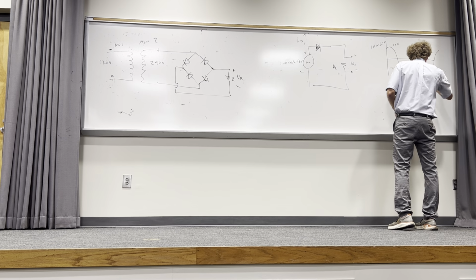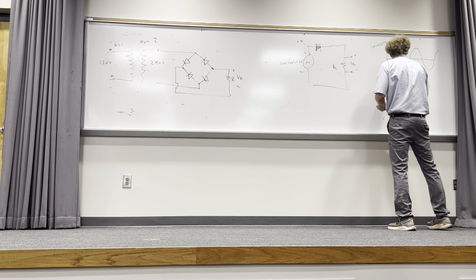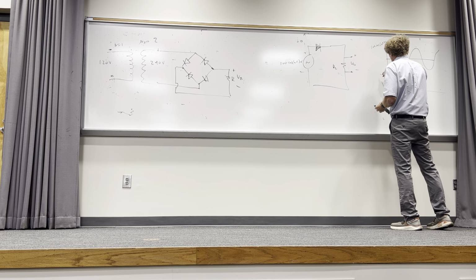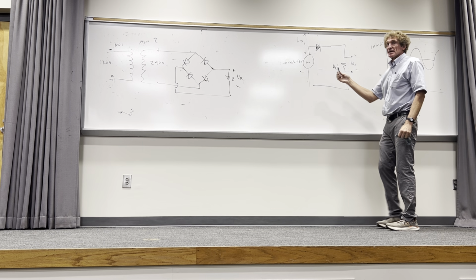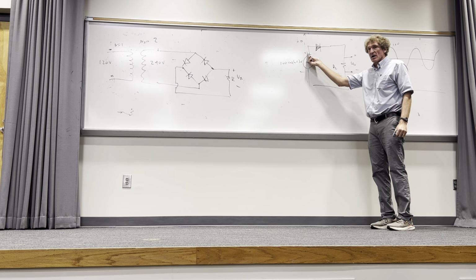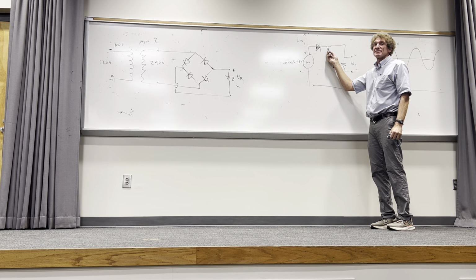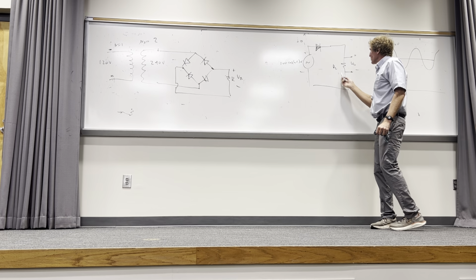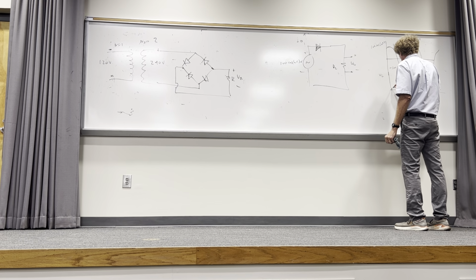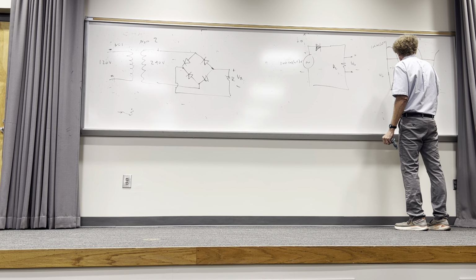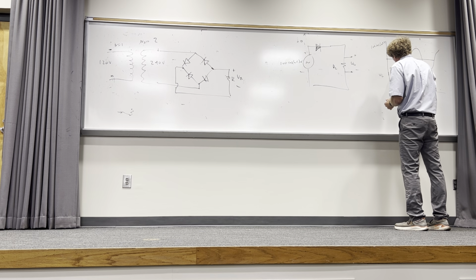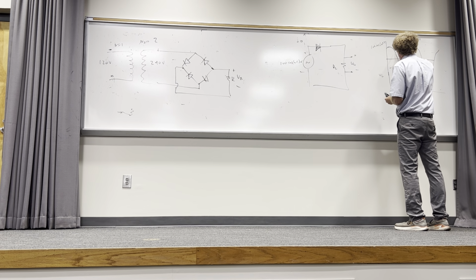Then, if you look at the voltage on the load, now listen, anytime this voltage is positive with respect to the bottom here, current flows through as if that diode doesn't exist. Y'all hear me? So all the voltage will be there, and it'll be absolutely tracking this.